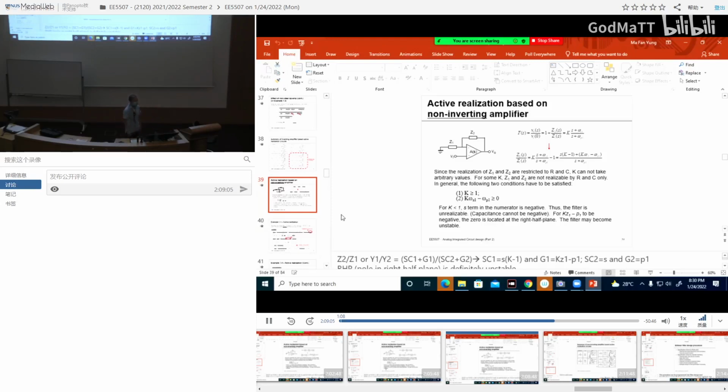So now you know why we talk about stability, why when you design op-amp, we always ask what's the phase margin, and how is the phase margin measured? How is it measured? What is the phase when the gain is 1? Do you ever think why it is defined like this? It's because you assume that the worst case is that I connect the op-amp in a unity gain.